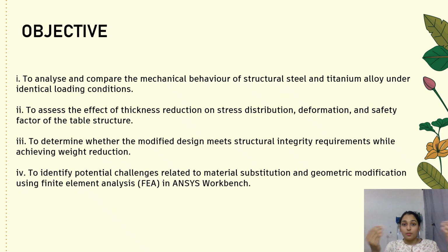It is a tabletop, a stand, a table connector, and a bolt that actually goes in. I have three models. First is the original design using structural steel completely for the table. Second is modification number 1. I've changed the material into titanium alloy. The third one is modification number 2, where I reduced the thickness from 10 mm to 8 mm for the tabletop.